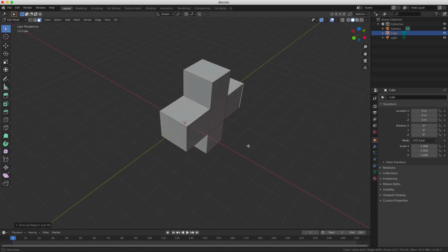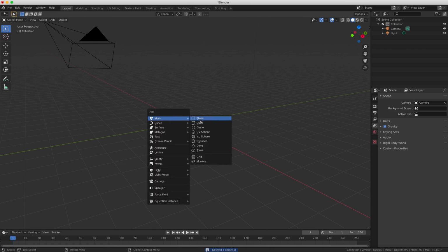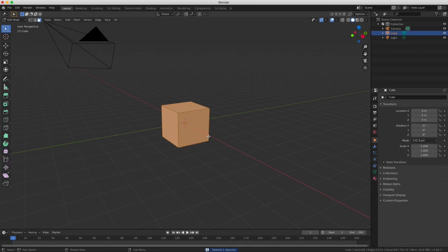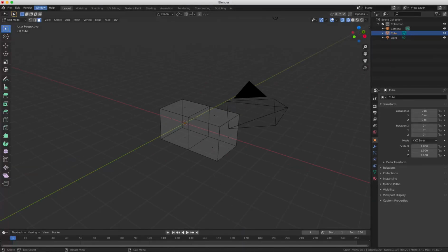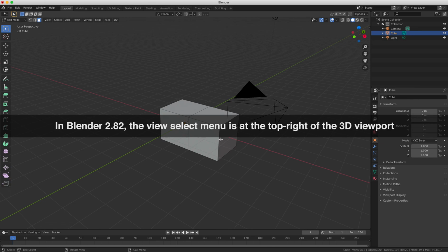For example, a dinosaur, which is what we're going to create now using the Extrude tool on our cube. Add a new cube to your project. So let's start by extruding one of the faces. Pull it out and then switch from solid to wireframe view. So when you extrude a face of an object, you lose the face that you extruded from. Blender does this automatically, which simplifies the geometry of your object and makes it render more quickly at the end. So go back to solid view now, and you can switch between your different views from that menu at the bottom of the properties panel.